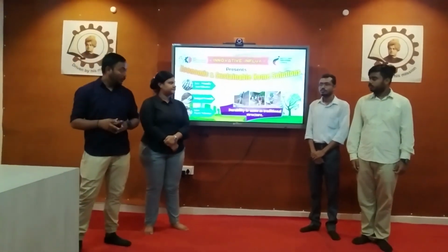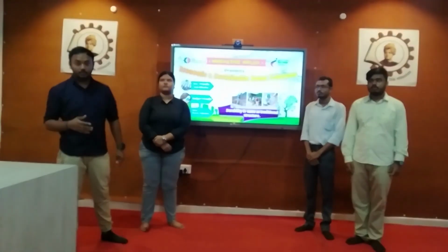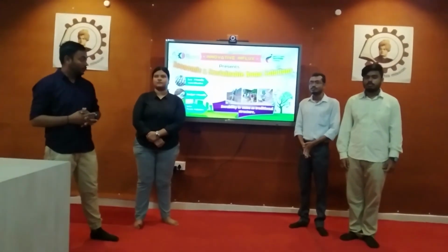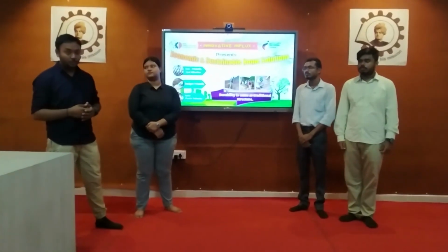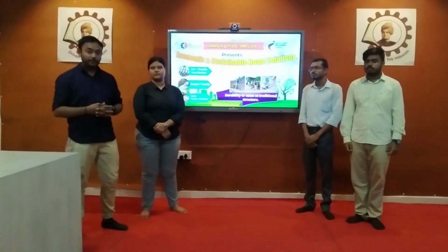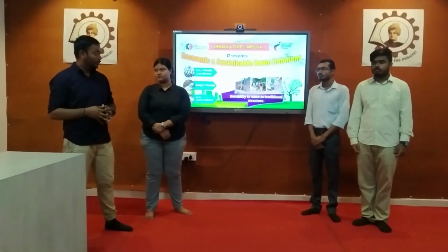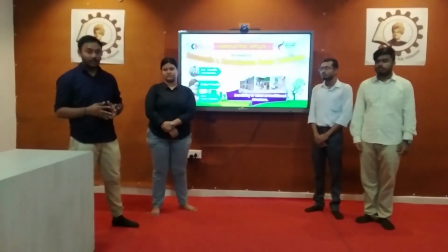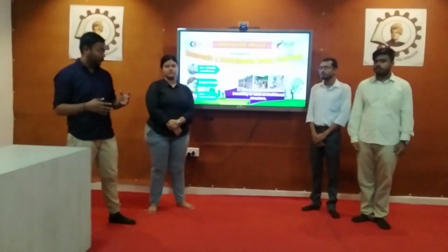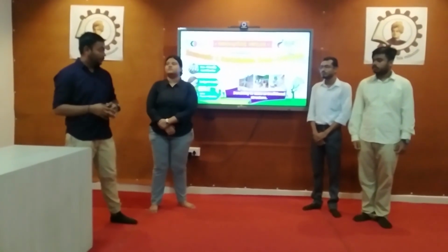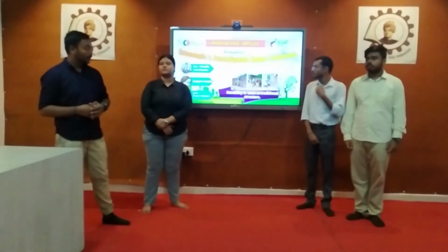And then we all know that in a building we have to provide RCC, I mean the steel structure, but instead of RCC or steel structure we will use bamboo, which is obviously chemically treated. As a plastering material we will use a mix of soil and other fibers like jute, and then we will apply cement mortar on it.